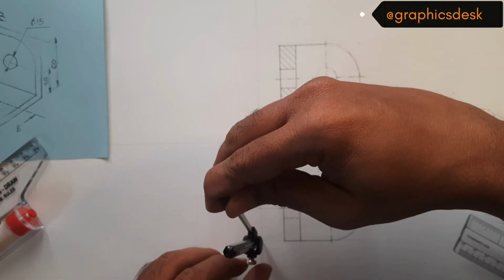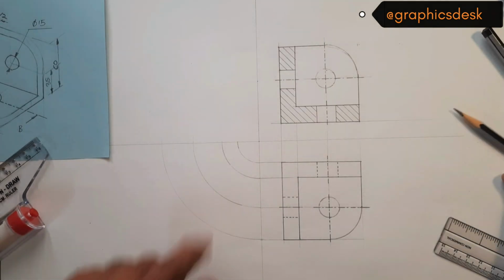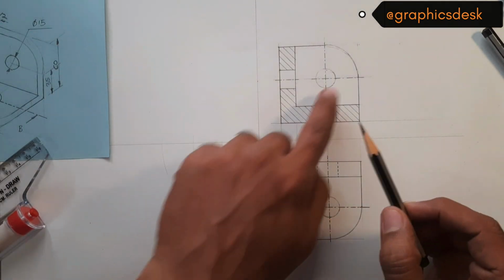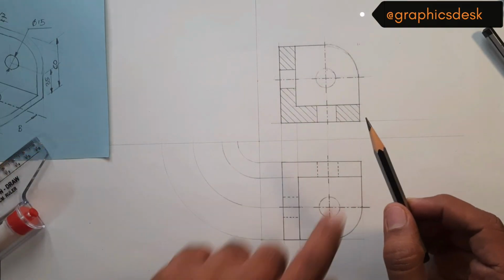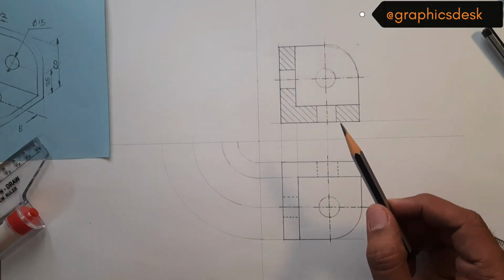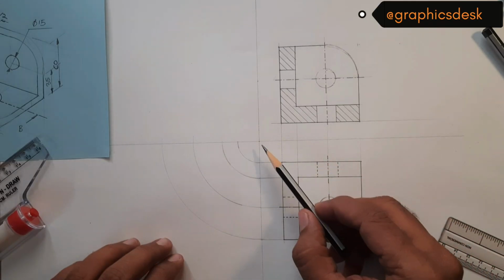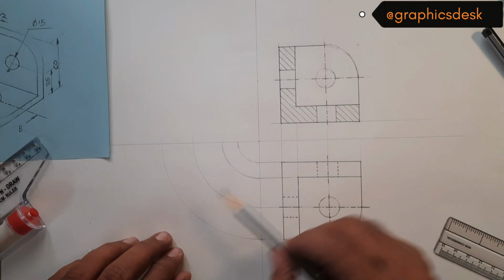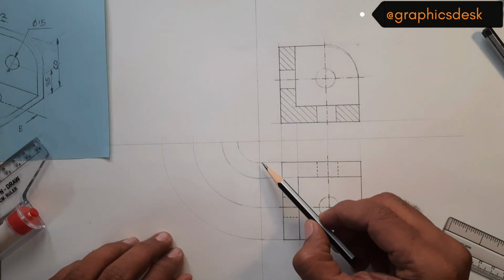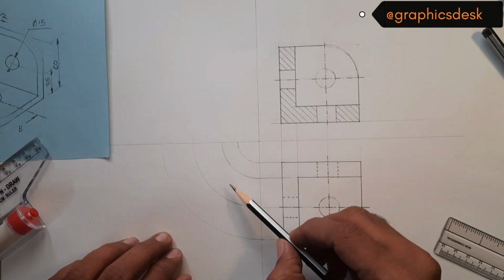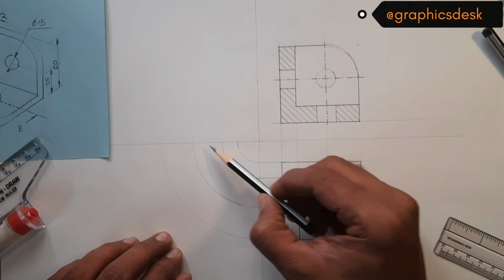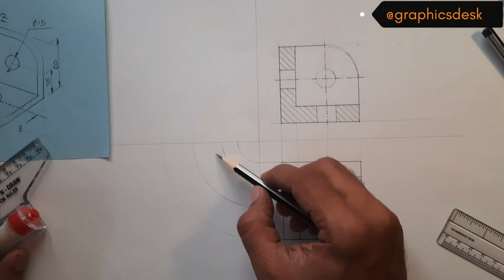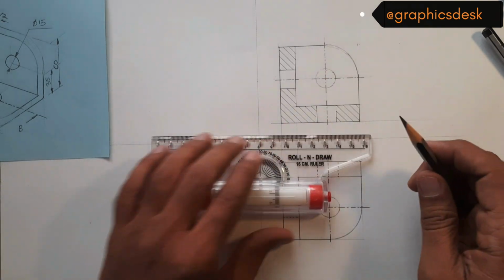Now we have taken all of these projections on this line. We have to draw vertical lines, and horizontal projections will come from this view. Now this is yet another method which works exactly the same way as I have shown in my previous video, where you are drawing a 45-degree line, and you don't have to use any curves, but the straight line from these points would give you these same exact projections vertically up. Now let me carry these projections and we'll look at the geometry here.